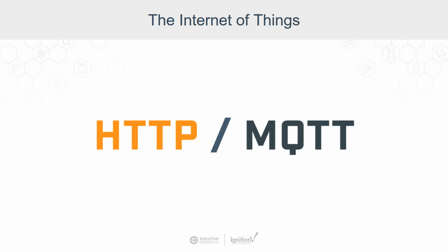What I'm trying to do here is explain that for the industrial world, and getting these applications and the data that's there, we are equating the Internet of People to the Internet of Things. For the Internet of People, it is HTTP and HTML. For the Internet of Things, it is MQTT and the Sparkplug specification, which is, again, that open payload specification for what is being transported.